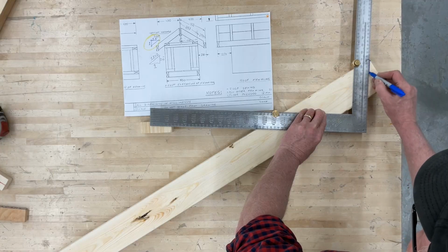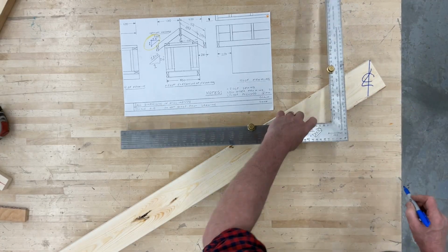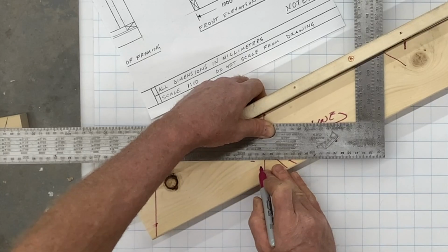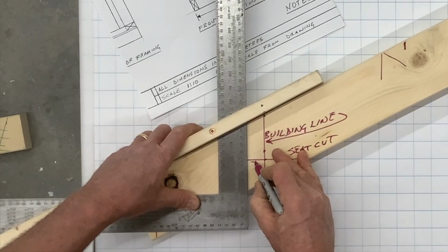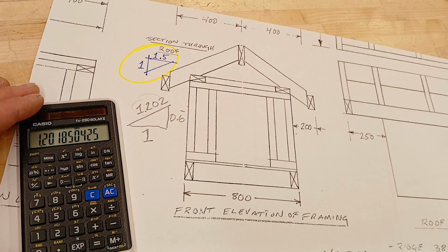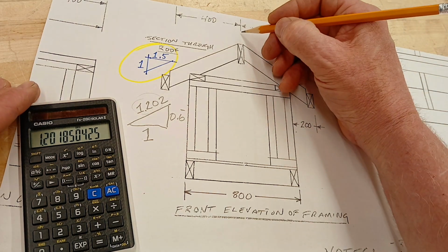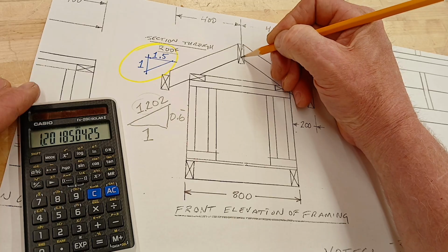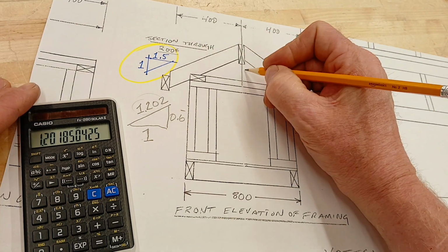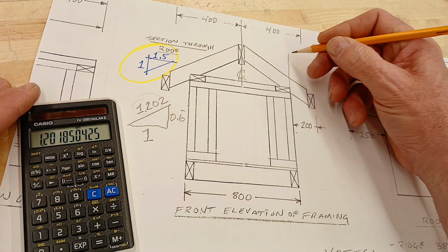If you're using a framing square for laying out your rafter, you may find that it's fastest to calculate the overall line length, mark that on your rafter stock, and then measure and mark your adjustments exactly like you do in the step-off method. I recommend drawing a diagram or drawing right on your plans to record every significant number as you go. The overall line length goes from the center line to the building line, so prepare extension and dimension lines to be ready for that number.